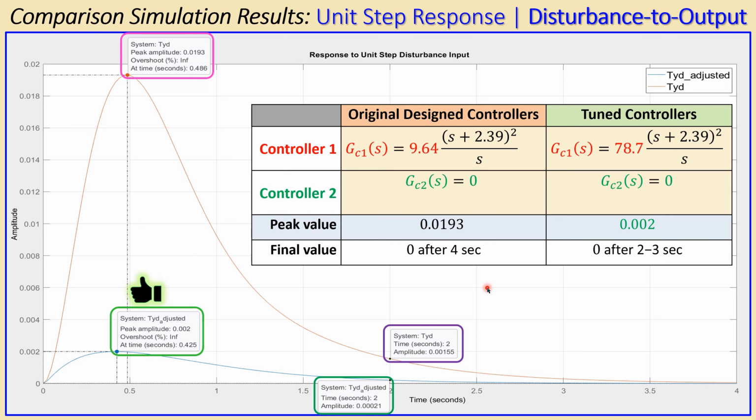Alright, this was example number 4 about the 2 degrees of freedom PID controller designs using specifically the given configuration. And in this case, we have seen that the plant transfer function has an effect on using a second controller or not. So you don't need a second controller necessarily. It really depends on the configuration and also on your plant or other parameters in your control system.